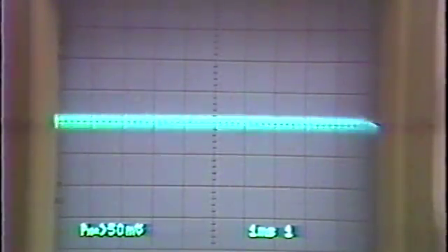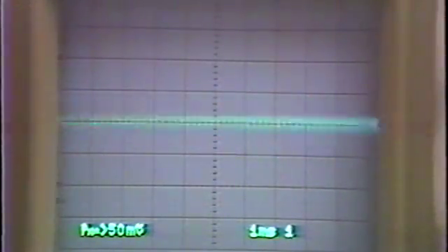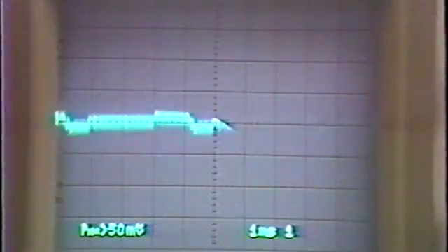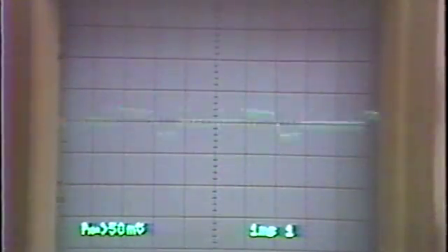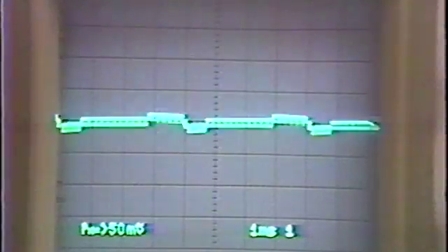Connect an oscilloscope to the digital to analog converter output. The digital to analog converter output waveform is at a low voltage level, so lower the voltage range setting of the oscilloscope. The waveform may be blurred and hard to see in some cases. If so, it can be seen clearly by passing it through a 2 kilo or 3 kilo ohm resistor.